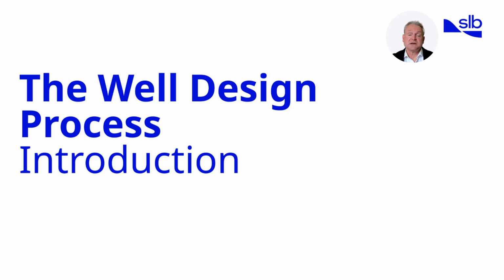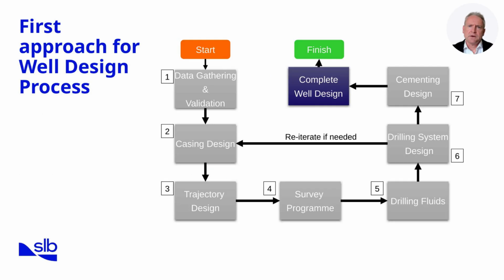In drilling engineering, the well design process is not a single-step activity, but a structured sequence that integrates multiple engineering disciplines. The first approach to well design always begins with data gathering and validation. Before any casing or trajectory decisions are made, we must collect offset well data, verify its accuracy, and organize it into usable formats. This gives us calibration points and benchmarks that guide the rest of the design process.